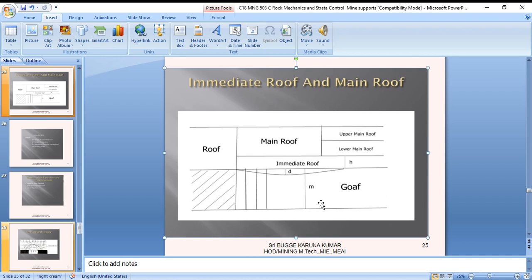The bulking factor k is easily determinable in the laboratory by measuring the relative volume of various materials before and after crushing. We found that broken rock occupies 60% more space than unbroken, but under pressure equivalent to the strata compression it will leave a volume about 12% larger than the original.